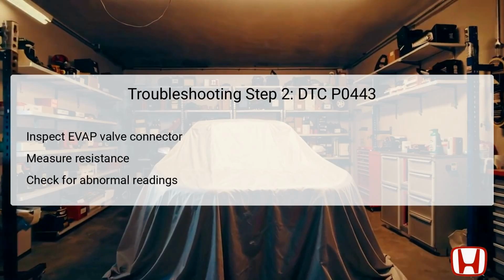The second step involves inspecting the EVAP canister purge valve connector. Begin by disconnecting the 2P connector from the valve. After disconnecting, technicians should measure the resistance of the valve's internal circuit using a multimeter. Under normal conditions, the resistance should range from 23 to 26 ohms at room temperature. If the readings fall outside this range, it indicates a problem with the EVAP canister purge valve itself, suggesting that it may need to be replaced.